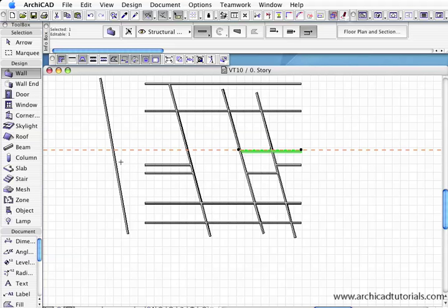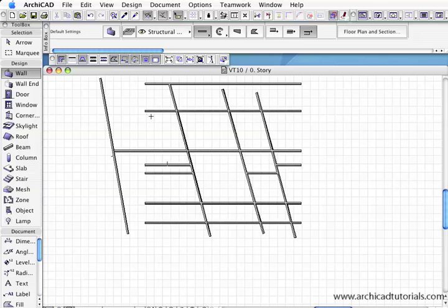Now if the wall is selected, that's the only difference, I'm selecting it. Now I'm going to move my mouse over to a Mercedes cursor on a wall or some sort of object. If the Mercedes cursor is up and I left mouse click on it, then it will shoot the object that's selected to that wall. So I'm going to select that wall, hold the Control or Apple key down, clicking, and the wall gets shot over. And if I left mouse click, it shoots it out. So trimming walls is just unselected, hold the Control or Apple key down, and if it's selected, by holding the Control and Apple key down, clicking, it will extend it.